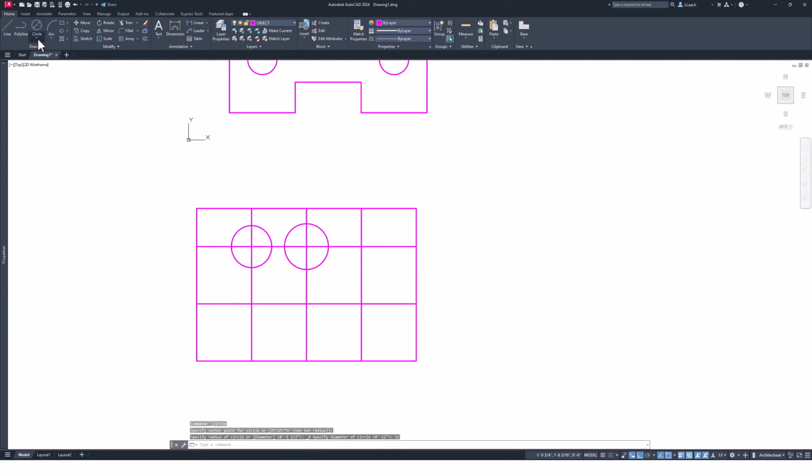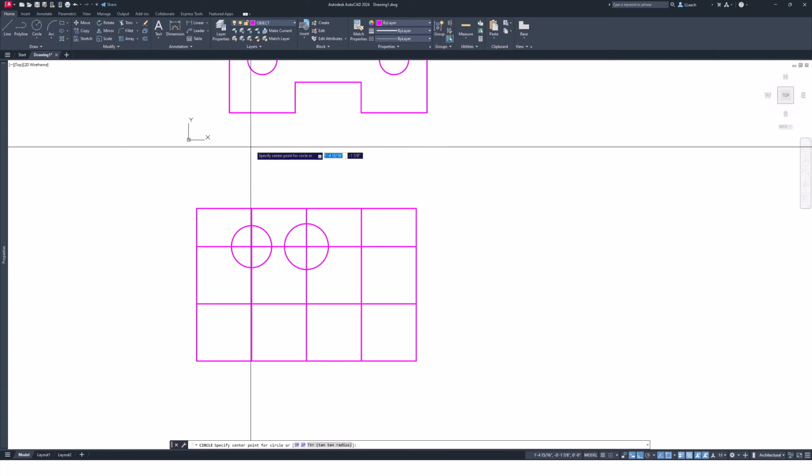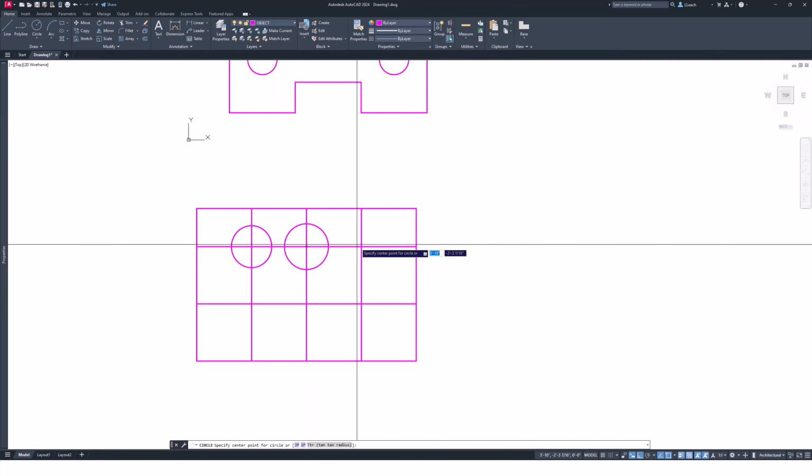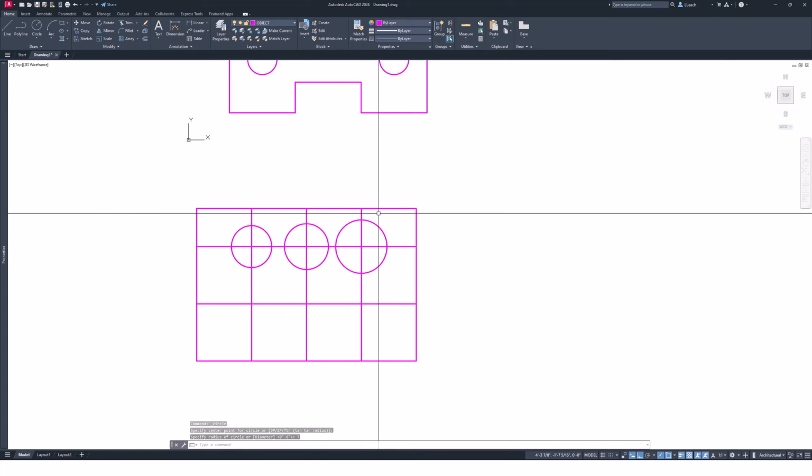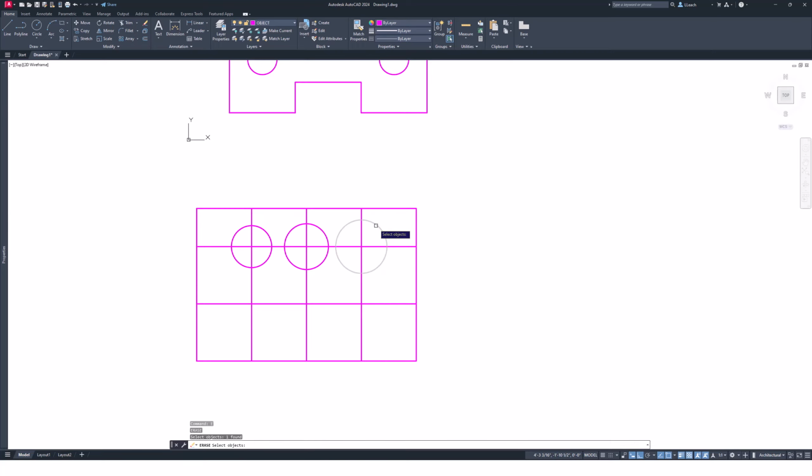Now, if you try to draw a circle, let's say you accidentally click the radius. I'm going to click radius, and so I'm thinking, okay, this one is 7. So if I type in 7, you notice, well, that circle looks super huge. What's going on? Just make sure you select the circle diameter option, not the radius option. So let me get rid of that. Just keep those in mind.